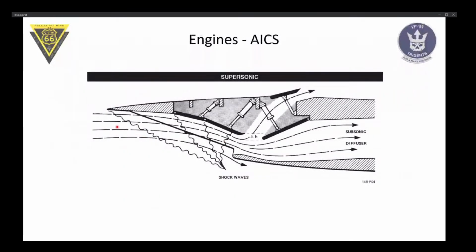And this way, you could transform all your kinetic energy into pressure energy and not lose any energy. Now, this is technically not possible, but what the F-14 engineers settled for is 4 shocks: 3 weak shocks and a normal shock. And this basically makes this transition from supersonic uncompressed flow to subsonic compressed flow as efficient as possible, which means not losing energy to entropy.